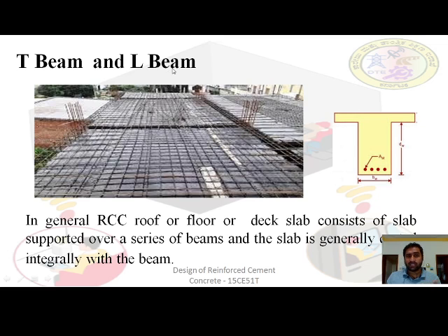Coming to the L-beam, here you can see the edge beam, where the slab is only on one side. Since the slab is only on one side and not on the other, only 50% of the slab will help to resist the moments in the beam. This resembles the shape of an inverted L, so that's why it is called the L-beam. So we have seen exactly what the T-beam and L-beam are.